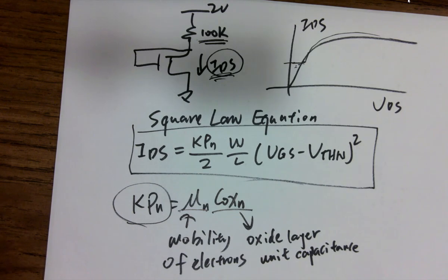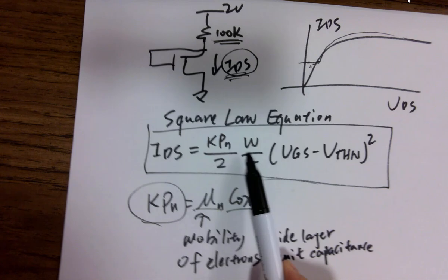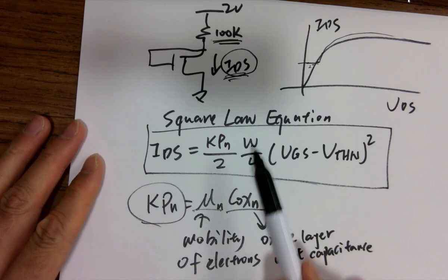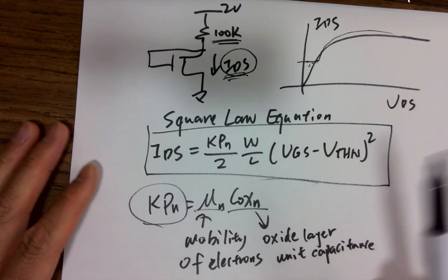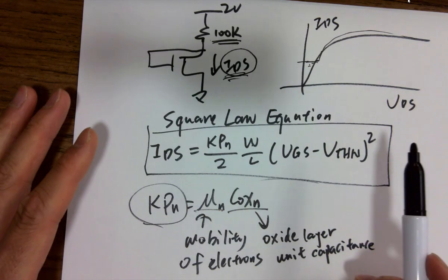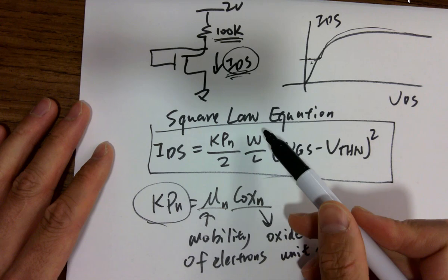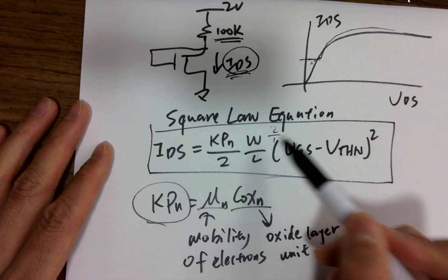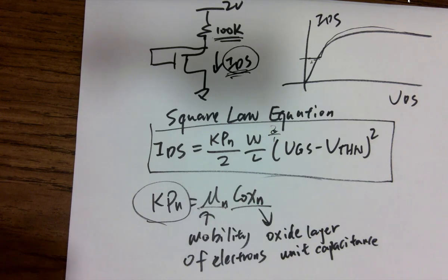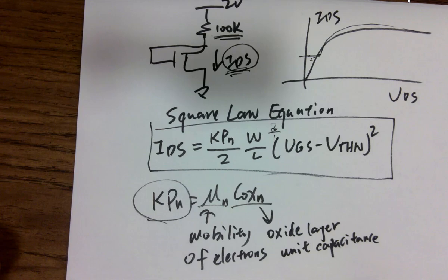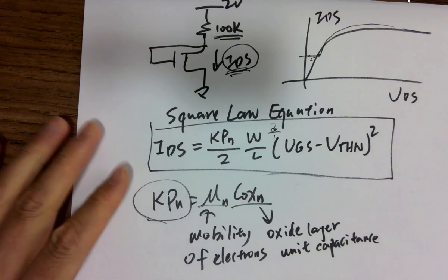So I told you there's a minimum length you can make, then just shrink the length and modify the width for different current. But usually we don't really have to modify this a lot, since the digital circuit is not really manipulating the gain and everything else as an analog circuit. Sometimes we do 2-to-1, sometimes we keep width and length the same for the transistors, to keep the smallest footprint. We just care about the logic. As long as the transistor is outputting a certain logic correctly, we don't care about the width and length.